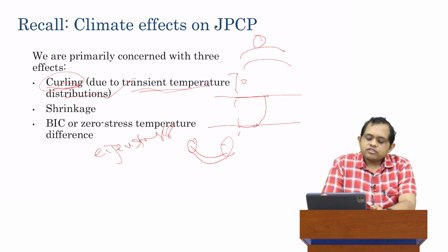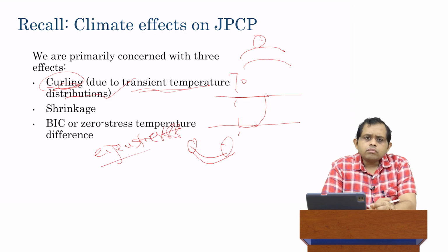The eigenstresses occur because this non-linear temperature distribution will try to warp the cross section of the slab in such a way that a section which was plane before this temperature distribution will try to be not plane. It will try to take a non-planar shape after the distribution is applied. But these slabs are usually analyzed using the medium thick plate theory or the Kirchhoff-Love plate theory.